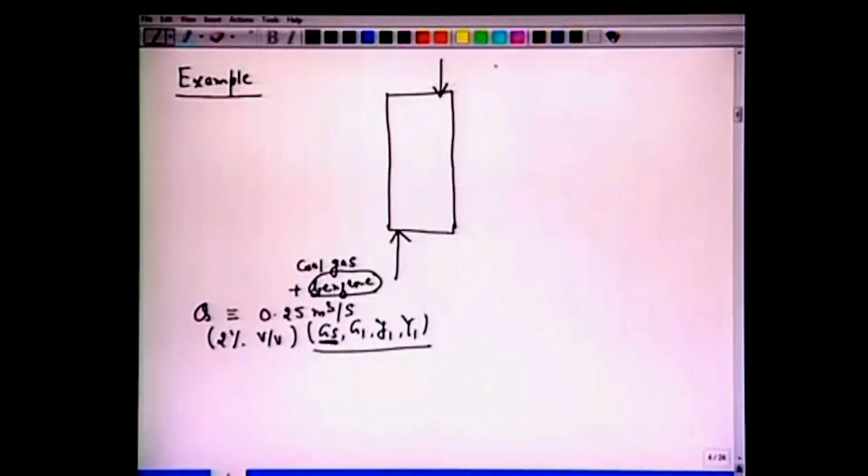To clean this, we have been given a wash oil. Okay, and this wash oil is not pure. In other words, if this location is 2 and this is 1 here, this contains small amount of benzene. So we can say that the small x2 is given, the mole fraction is 0.005.